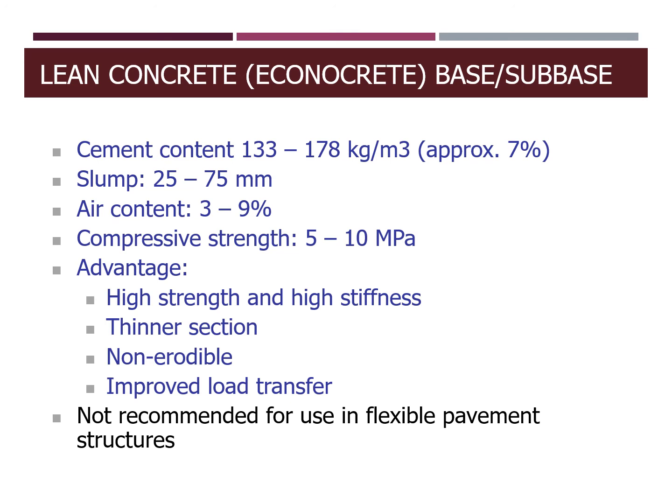First, this kind of base will have very high strength and high stiffness. In that sense, it's able to provide strong support to the upper layers. Also, it's in a thinner section so that the pavement depth won't be very high. Also, the concrete is not erodible, so it can last for a longer time. And this one can provide some improved load transfer from top to the bottom.